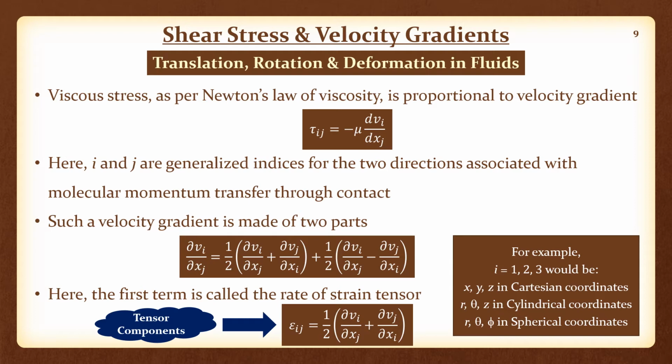Instead of writing out the 9 components, and even more painfully, instead of writing out tau xx i plus tau xy ji plus tau xz ki plus, and so on and so forth, writing out all of that, in a simple fashion, it is possible to represent that second order tensor as tau with a subscript ij. This, you would see, is the most commonly used notation for representing tensors in advanced books in fluid dynamics as well as in transport phenomena, right?